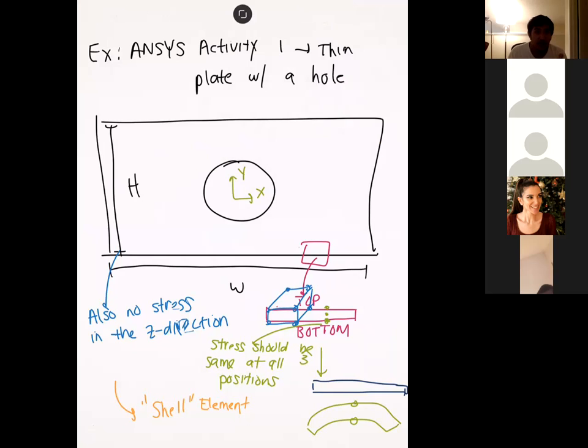And so in that case, you have a big change in the stress as you go through the thickness of the beam, okay? In that situation, even though geometrically the beam itself might be very thin, I would really hesitate to use a 2D simulation, because you have that gradient of stress throughout, right? You go from maximum tension to maximum compression in that very short amount of time, right? And if you run a 2D simulation, you're just going to lose all that data altogether. And so, unfortunately, it depends on the situation.